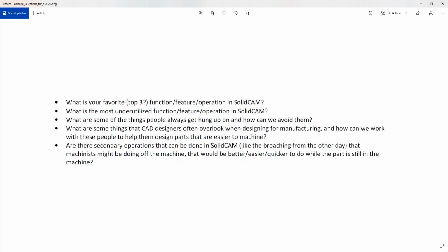Okay, so Kevin and I both agree on that one. HSS in general, I think, is a good toolpath because when you're doing finishing, a lot of the times it's about the look of it, right? I mean, that's why we're finishing it. So HSS, morph between boundary curves, gives you the ability to really smooth things out as you go across a particular surface. Sometimes you have to modify the parameters a little bit to make it look better. But in general, starting with that, you'll get a good finish on your surface.